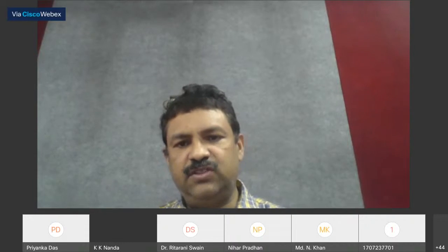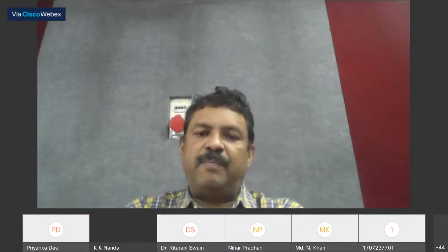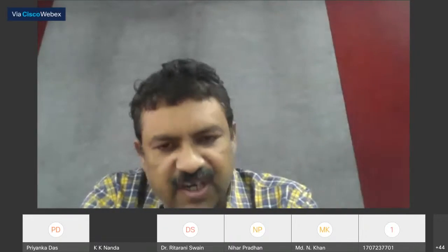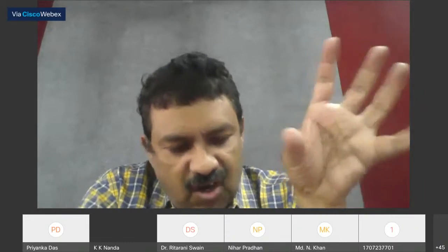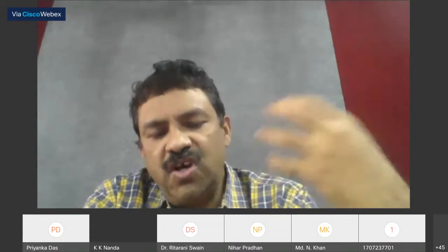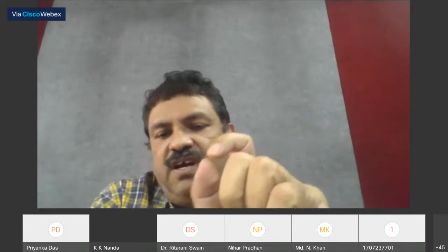In this case, as you see, I have taken a resistance versus temperature curve from the Journal of Applied Physics, and tin oxide being an insulator. Okay, we also call this a semiconductor because the conductivity actually falls in the range of a semiconductor. There is oxygen deficiency, and that leads to N-type conductivity of SnO2. And this is the resistance versus temperature curve of a SnO2 thin film in oxygen atmosphere. That is interesting, as you see here.